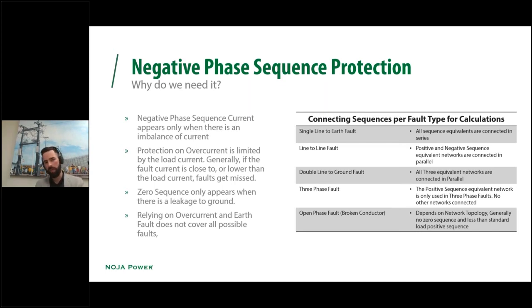short-term overload that you can take on. So some circuit breakers have an overload that you could, in high demand, provide extra power for a short period of time. But if that's starting to encroach on what your protection configuration is, negative phase sequence gives you a way to pick out those asymmetric fault conditions because it's looking for imbalance.